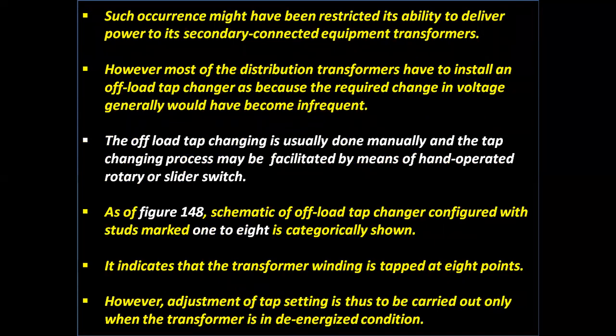Such occurrence might have restricted its ability to deliver power to its secondary connected equipment transformers. However, most of the distribution transformers have an off-load tap changer installed, because the required change in voltage generally would have become infrequent.